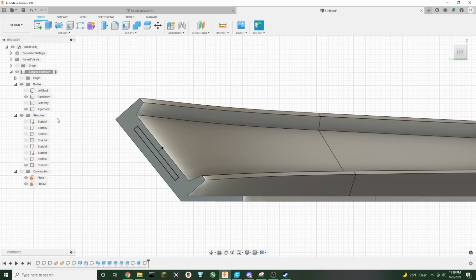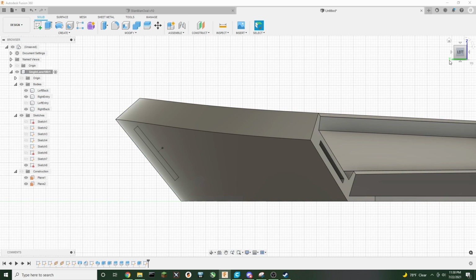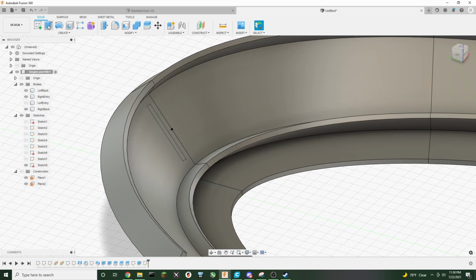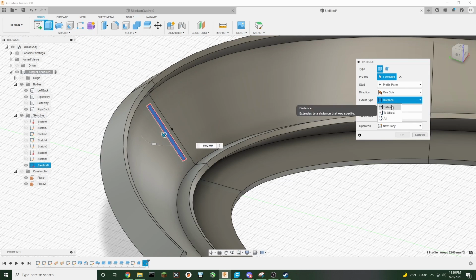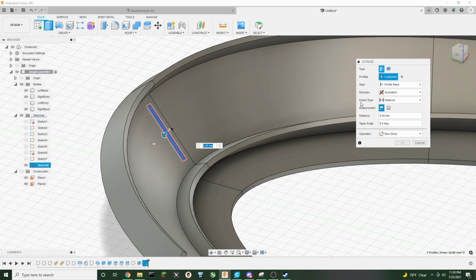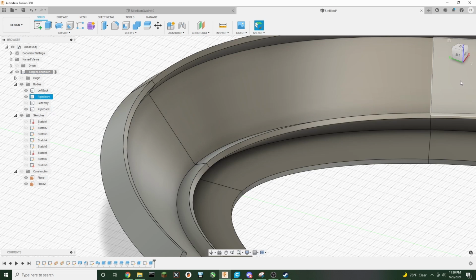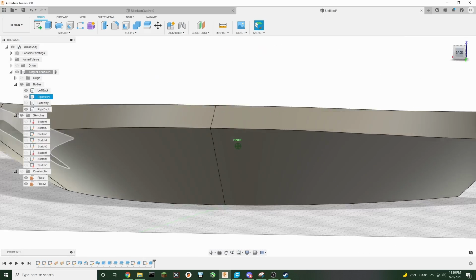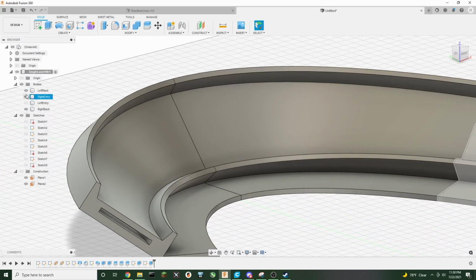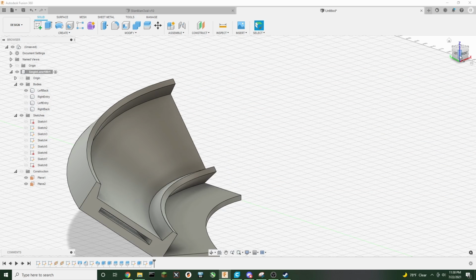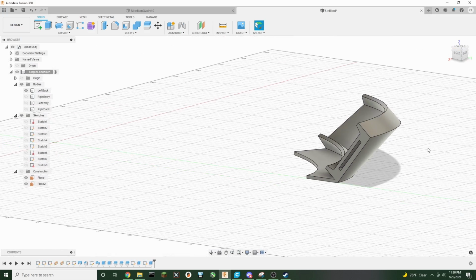Finish that sketch. Bring back the left back. We're going to extrude it both ways. Symmetric. 21 millimeters. Cutting. It did not penetrate. That's awesome. Get rid of left back. It's there. Get rid of right back. It's there. Sweet.